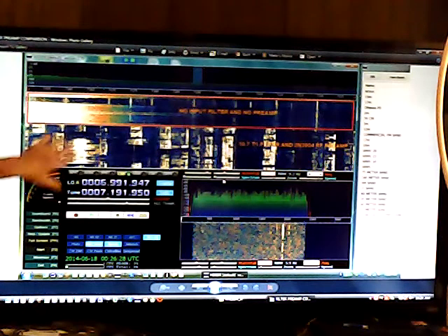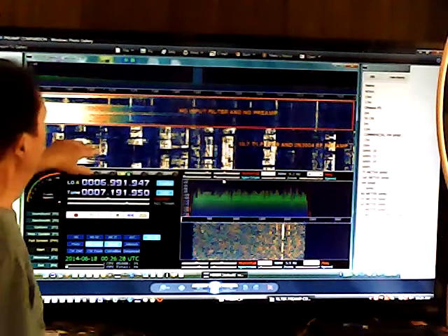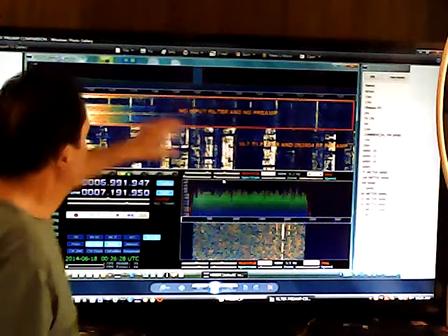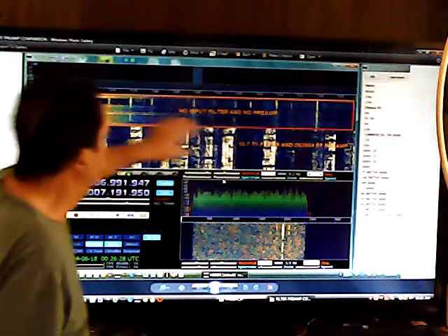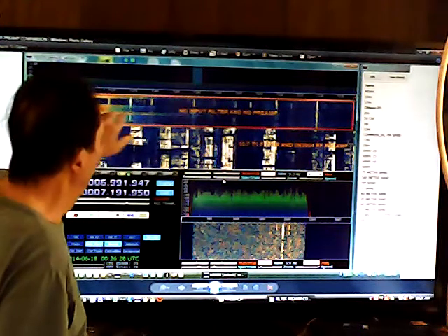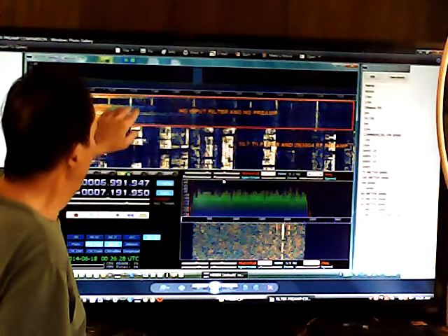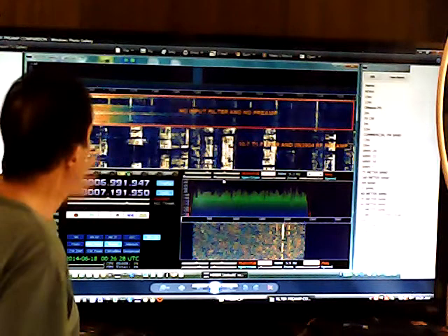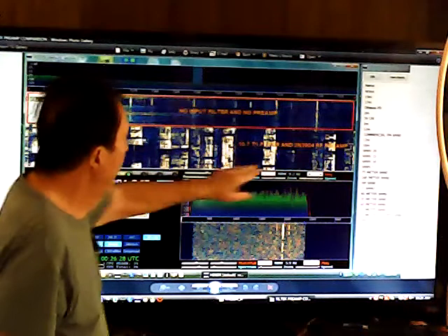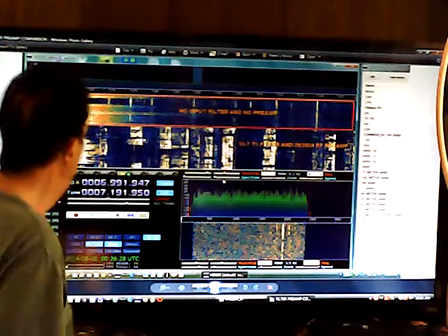I've done a split screen here to show you the effect of using that antenna tuner, Preselector. Without it, you're going to get all sorts of broadcast band interference. The signals will be there, but you'll have so much interference from other powerful stations, it will not allow you to have a good, clean, operable signal. With an ATU, you'll be able to define every individual signal and carrier.